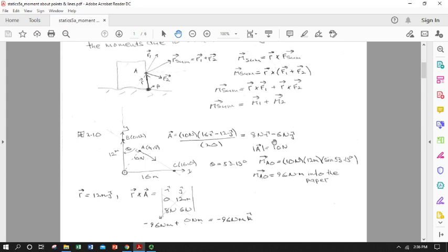So I'm going to use this in a cross product, and now I just need a radius. Well, I could work really hard with geometry and try to get a true perpendicular, or I could use a cross product and say, just give me a point anywhere on that line, and I'll use the cross product to make it perpendicular. That tends to be my favorite because I don't like trying to envision complex geometry. I think it's easy to make a mistake. If I know what the points are and I execute a vector product properly, I know I'm going to get the right answer. And of course, you have to execute it properly.